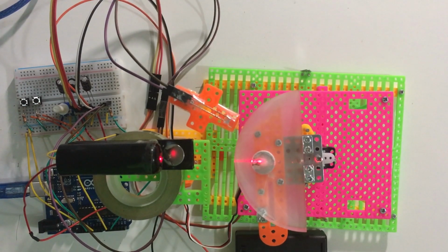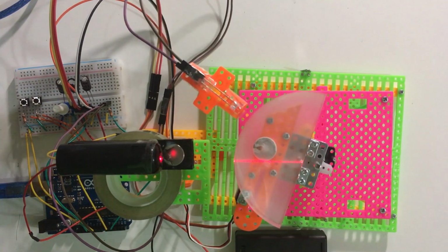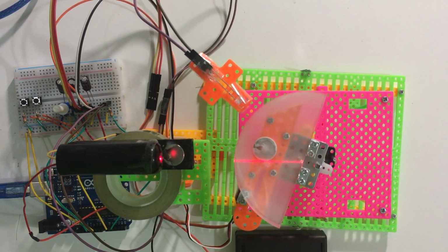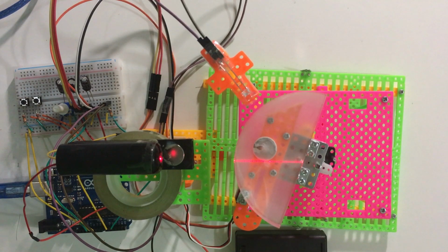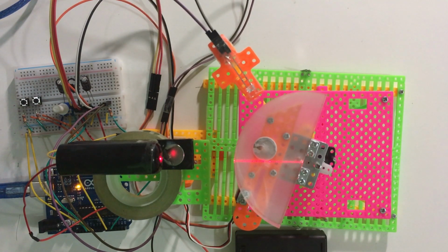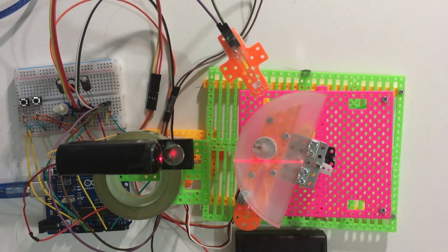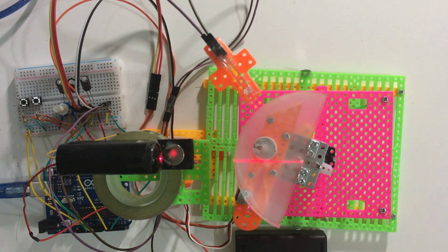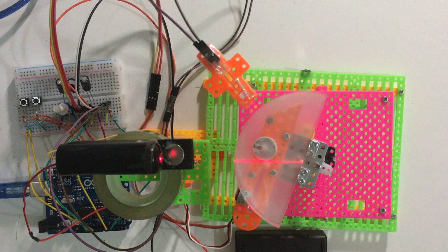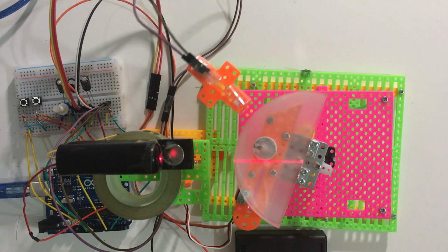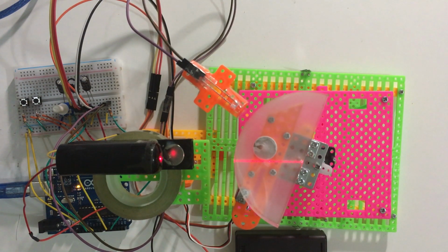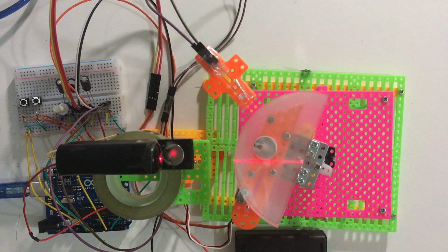Next, I'm gonna push the first button to start running the entire loop for the auto mode. The sensor arm is at the initial position, and the upper servo turns to the initial angle, which is 20 degrees in this case. In each loop, for the sensor arm to take the data of 30 degrees around the supposed reflected angle, there are two parts.